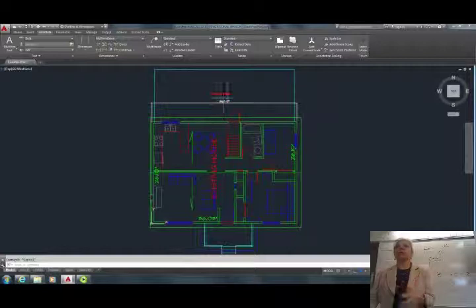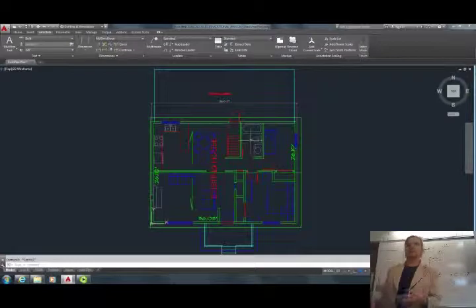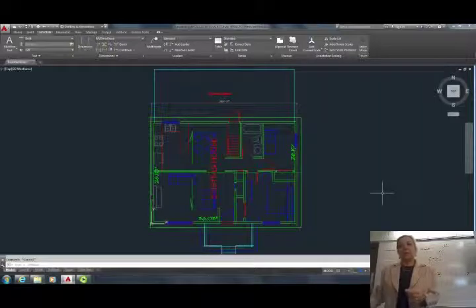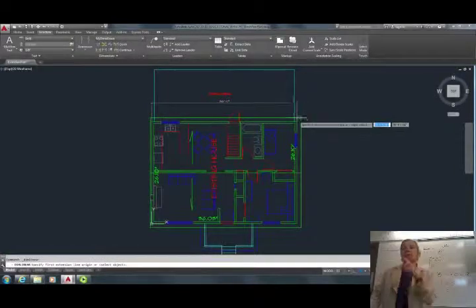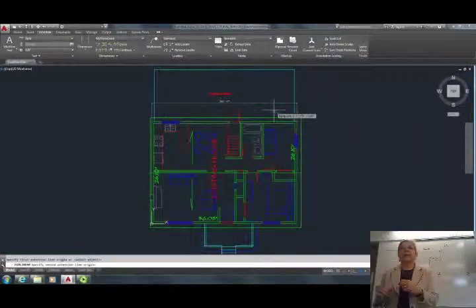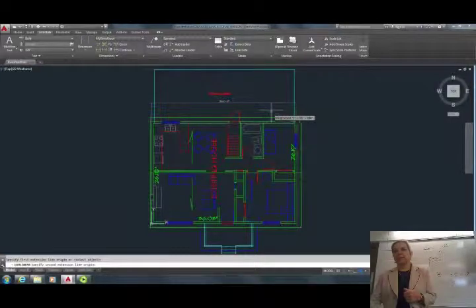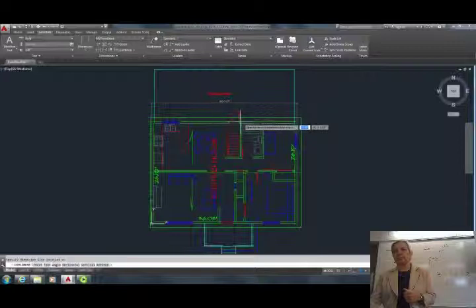So your overall dimension for your addition should not be 36.1, right? The builders don't want to build an addition that's 36 feet 1 inch. It should be 36 feet, unless there is a reason why that 1 inch is there. But more importantly, all dimensions in the string have to add up. So your next string should show all of the jogs, if you have them, and then the last, third string shows openings. So you should be now zooming up closer, making sure you're picking up the right points.